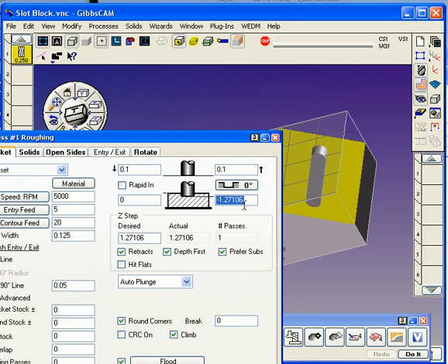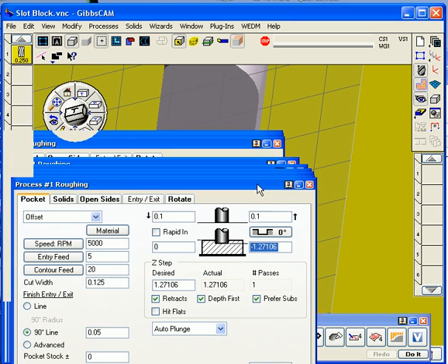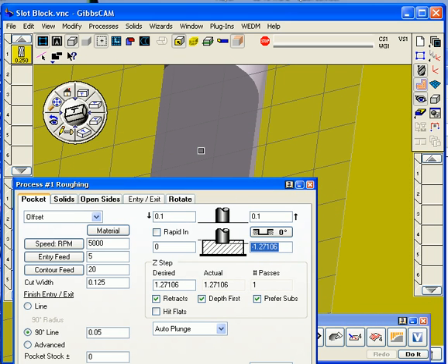Further, what depth is that pocket? I'm going to zoom in here a little bit. How deep is that pocket feature right there? Make sure that the depth dialog box is active where my blue cursor is. Hold down the Alt key again and click on that face, and that's 3/4 of an inch deep. So let's divide that by 3.